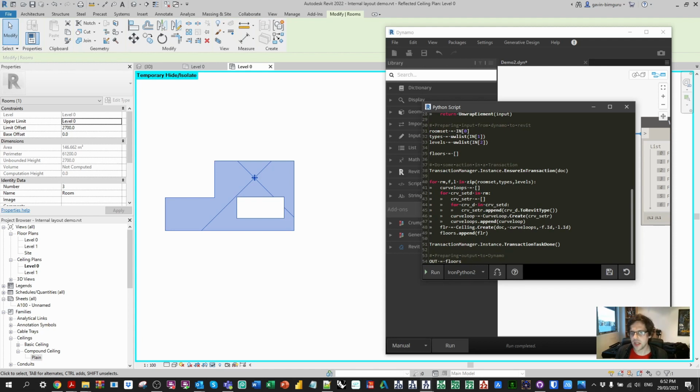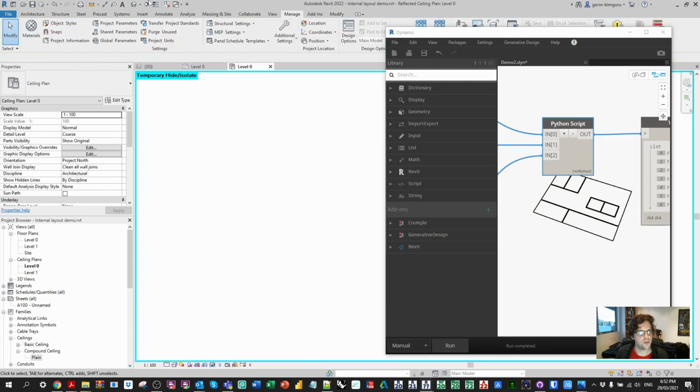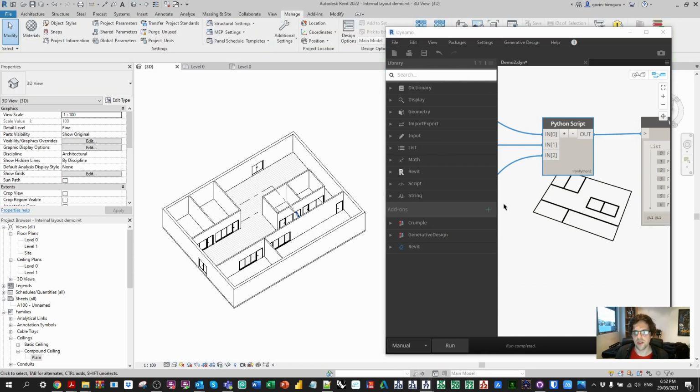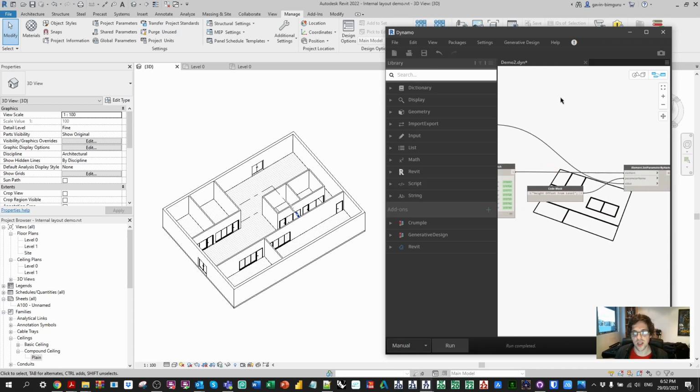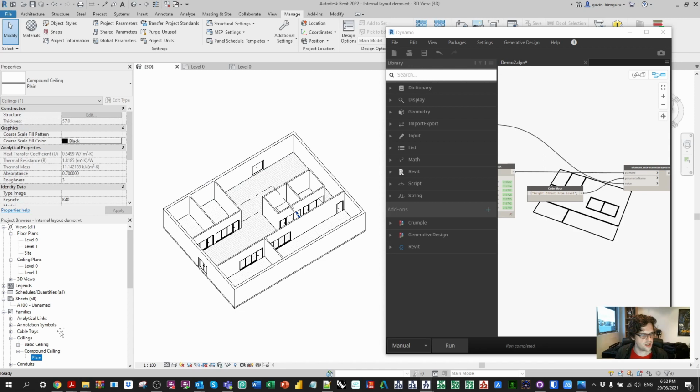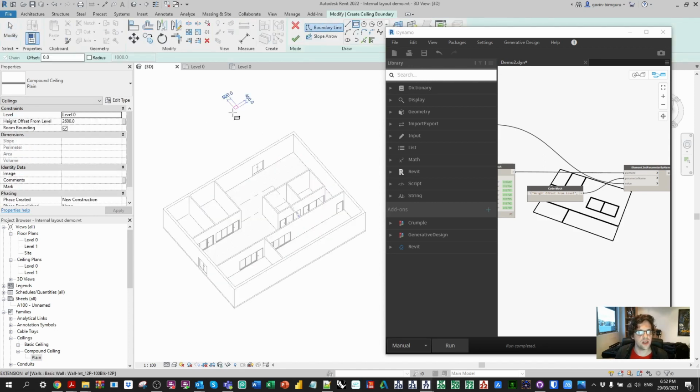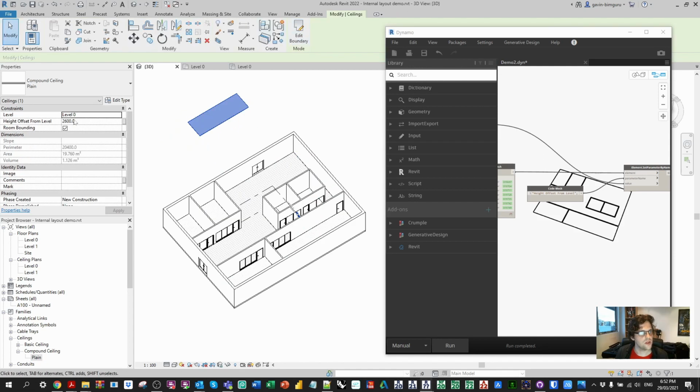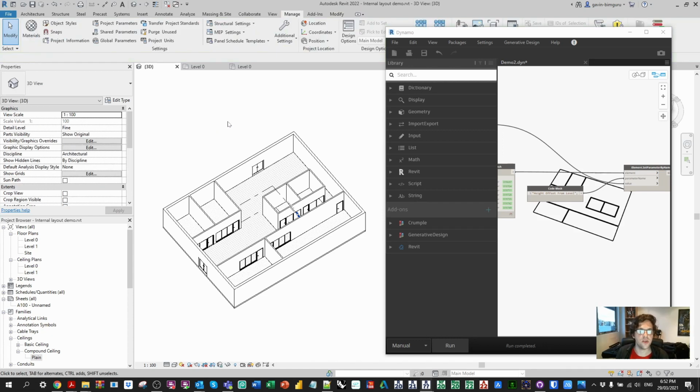ceiling.create. Now I could go and rename floors, ceilings, etc. Who cares? It's all in the Python node. I think this should work. If it does, I'll be pretty excited because it shows how similar these methods now are, which is really what the Dynamo team was aiming for. The last thing we might want to do, and I just need to check the name of this parameter when I place a ceiling, is what the height offset parameter is called. It's also called height offset from level, so fingers crossed it's also called that in Dynamo.